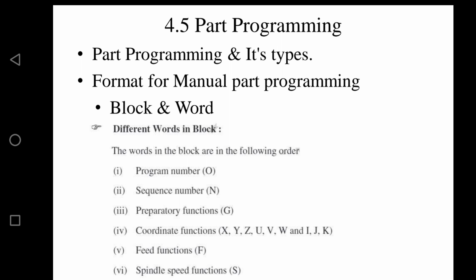O8999. Well, I said the program number is a 4-digit number, so we can write it from 0 to 9999. General programs take up to 7999, and macro programs take up to 8999. What about the rest, 9000 to 9999? Those are taken by the machine tool macro programs.